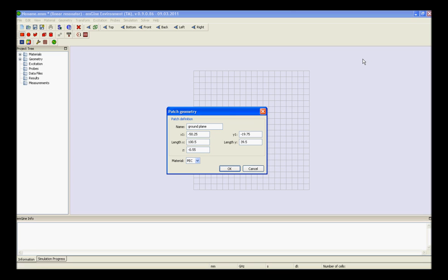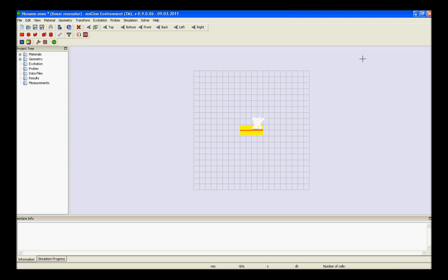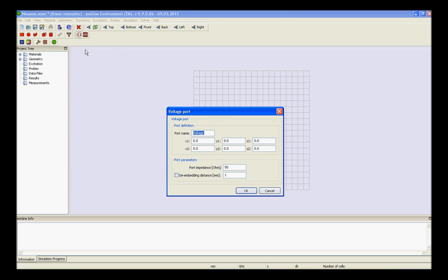and press OK. The next step is to add the ports to the linear resonator device, for which the S parameters will later be calculated. Each port will simulate linear resonator structure that is connected to the structure at the ports plane. Voltage ports are the most accurate way to calculate the S parameters of any microwave device and should thus be used here. To define port 1, go to the excitation, then choose a voltage port and provide the values in the open dialog box.